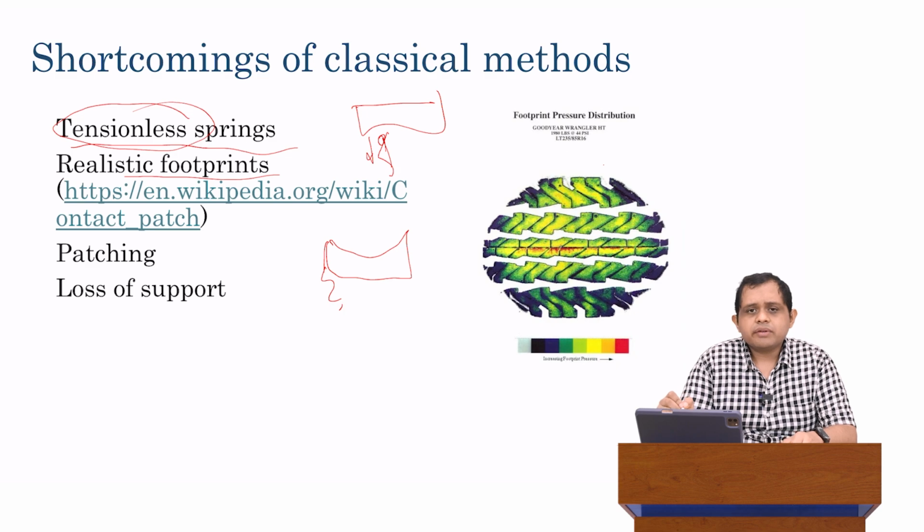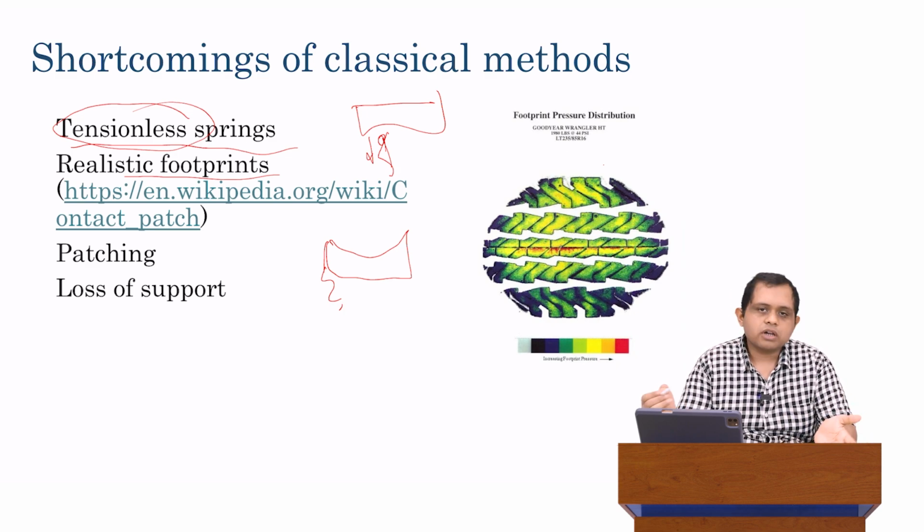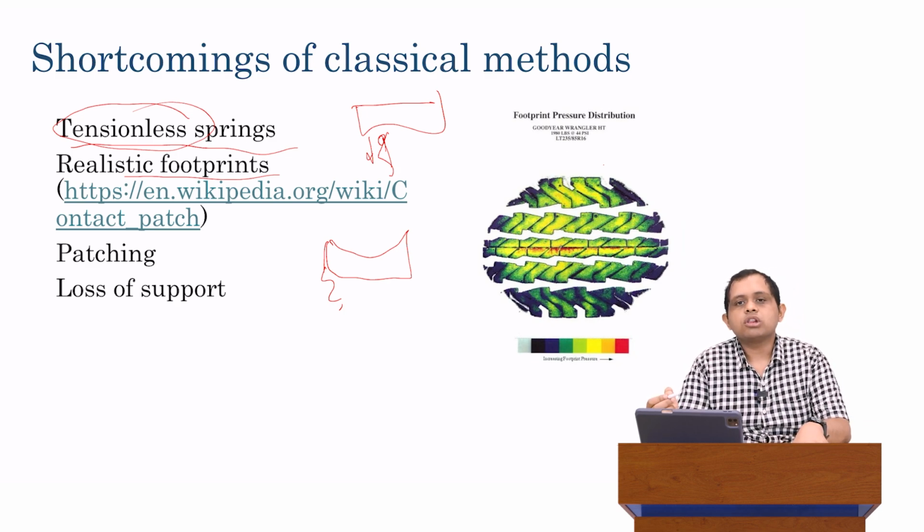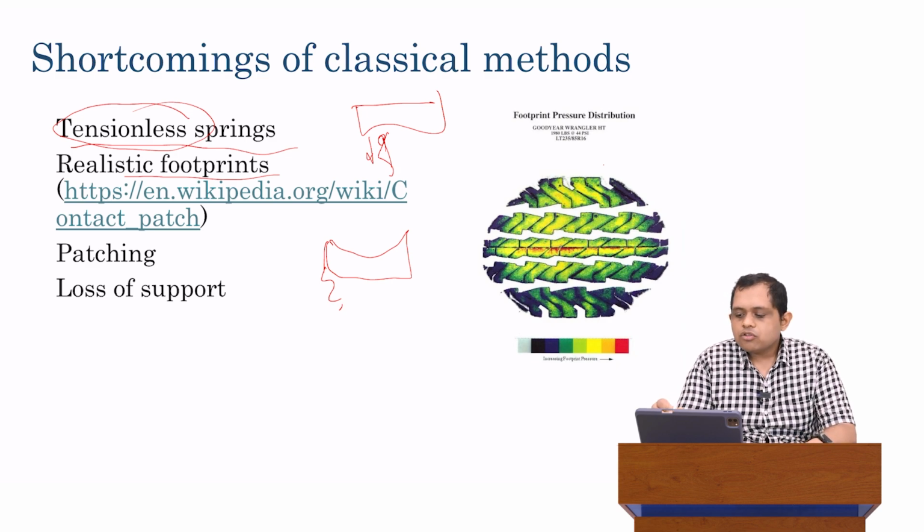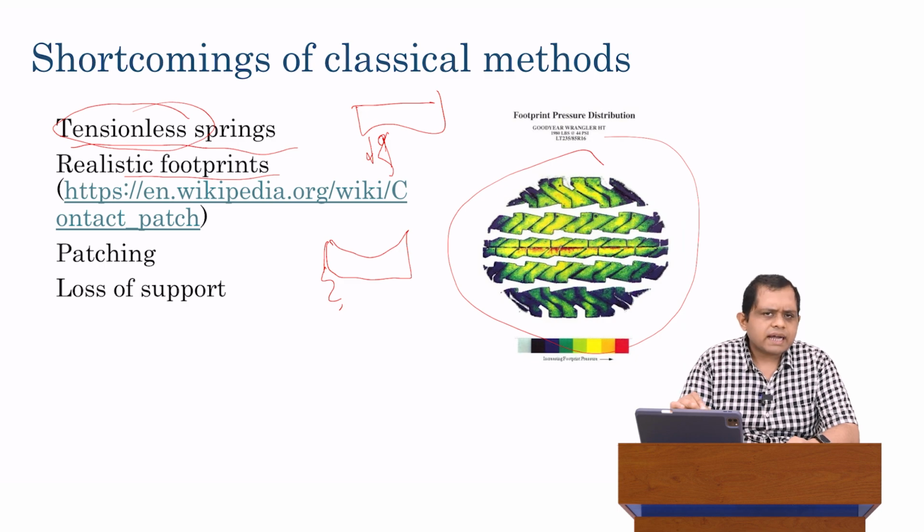And a relatively easy way to do this without getting the numerics is that you could actually just drive a tire, let's say, over some ink and some paper, and you can see what the distribution or what the footprint of the tire is. So this diagram which I have over here, it gives an example for a certain tire. Every tire has its own footprint. Every manufacturer designs it slightly differently. So this is obviously just one example. But what we see over here is, first of all, it's not circular. That I think is quite obvious from the diagram.